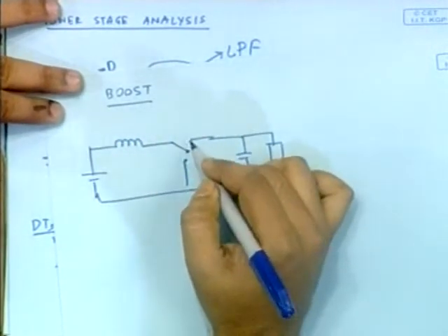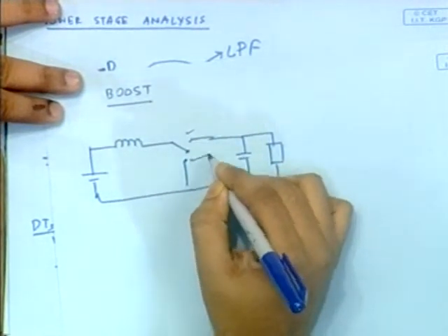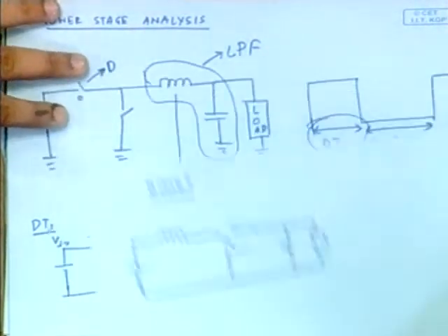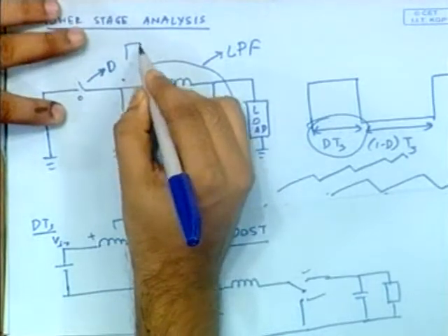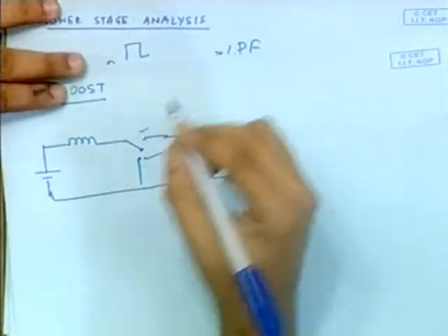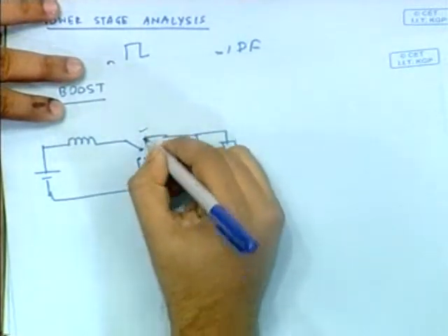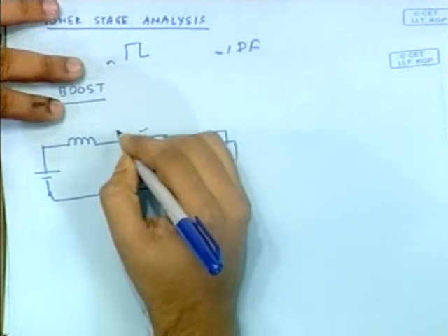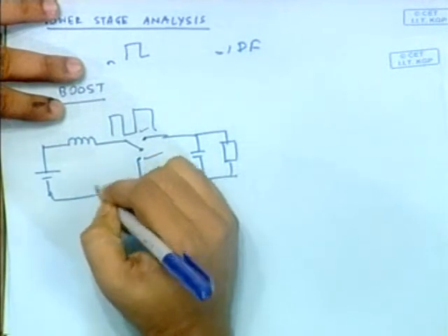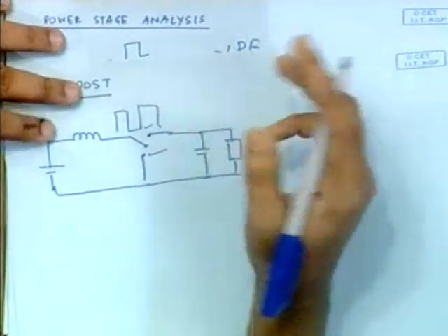Now when you consider the two circuit configurations, in which once it is connected to this and another time this is connected to this, you cannot just isolate a square waveform. In the earlier form you could say that it is a square waveform because one side is constant, this is V in. Here it is in between two circuits, alright. It will be a bit difficult. And even if I assume that V output is constant, and we say this is V output, you will get a square wave here, but then you don't have a capacitor here, so it's not very straightforward. You'll have to do a lot of Thevenins and all that stuff to average this out. So let's apply the volt second balance and practice it.